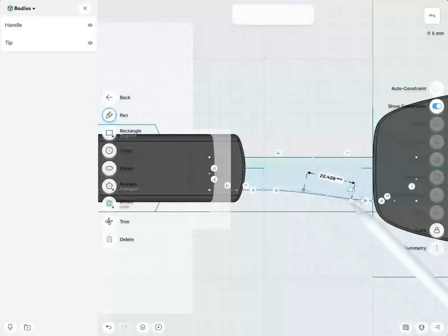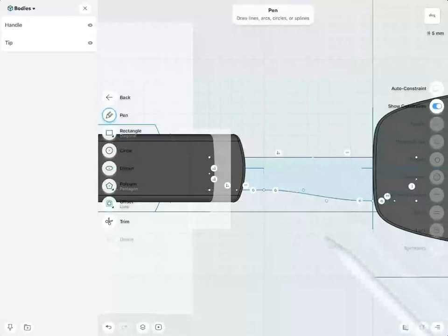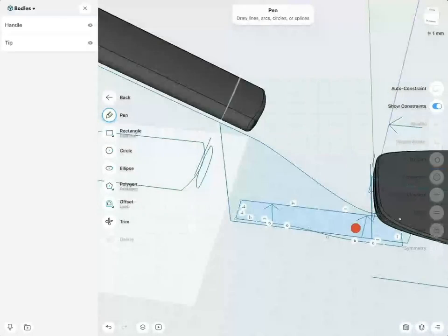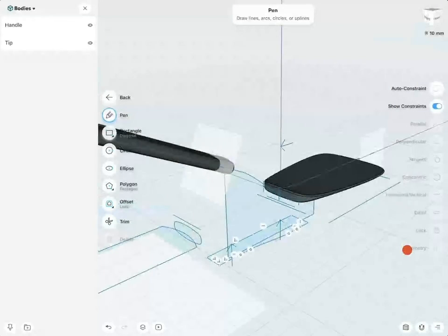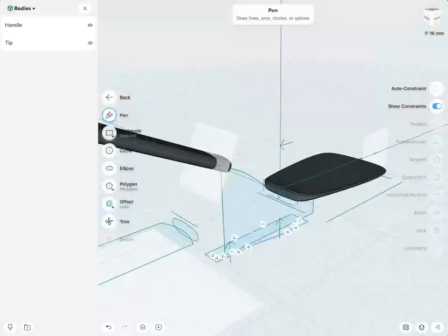Now we'll increase the bend a little bit. So a pretty good technique is we work with 2 profiles and then create a solid model, and then we create an edge, and the edge we will use as the path. So we don't use a sketch, we use the edge of a solid object. So this might sound a little bit confusing.